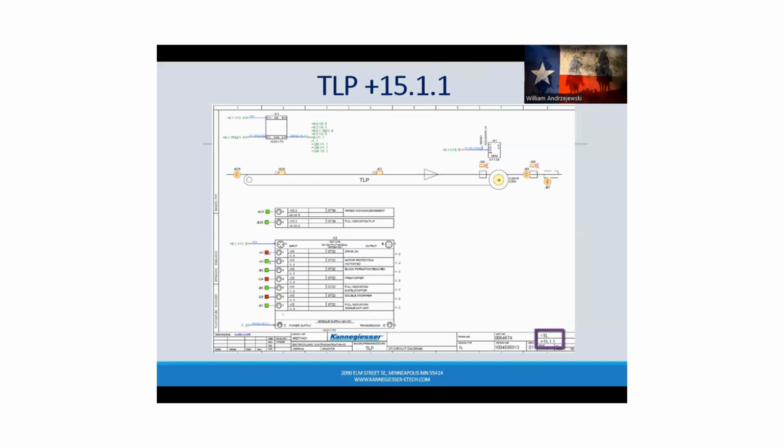So over here, we had another conveyor and it transferred. Whenever we transfer, we are always monitoring that transfer. We've got to have something that says nothing is blocking the area between the two conveyors. So we're monitoring that. Don't worry about what kind of sensor it is. There is some sensor there monitoring.